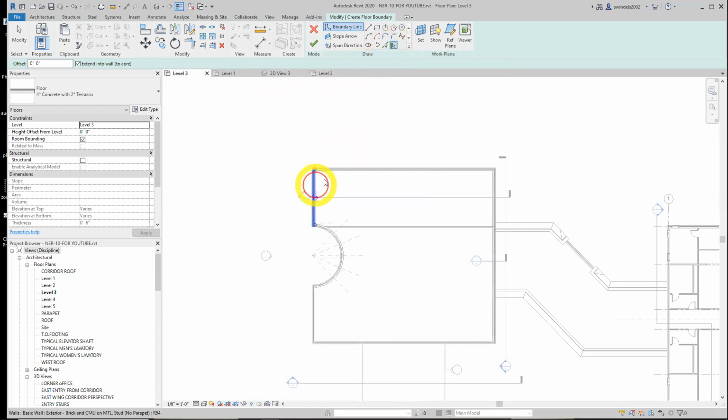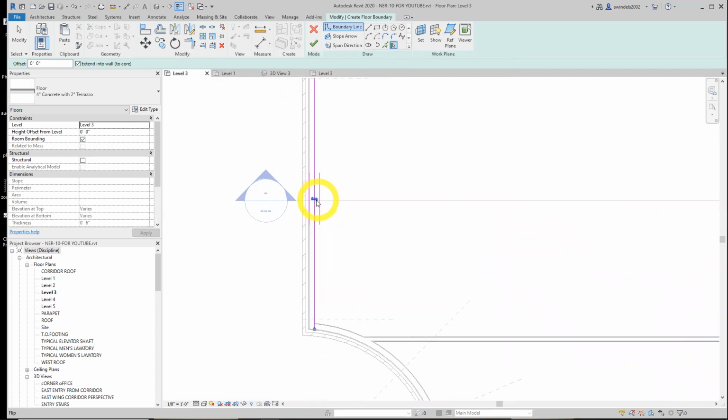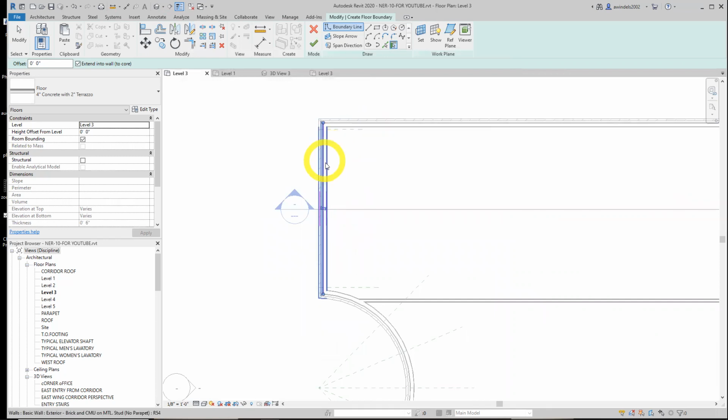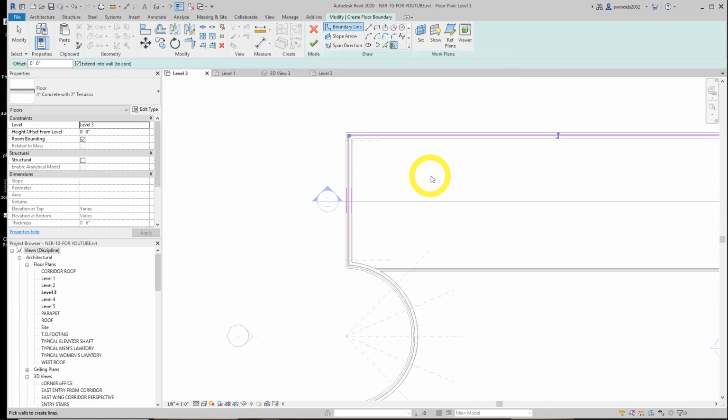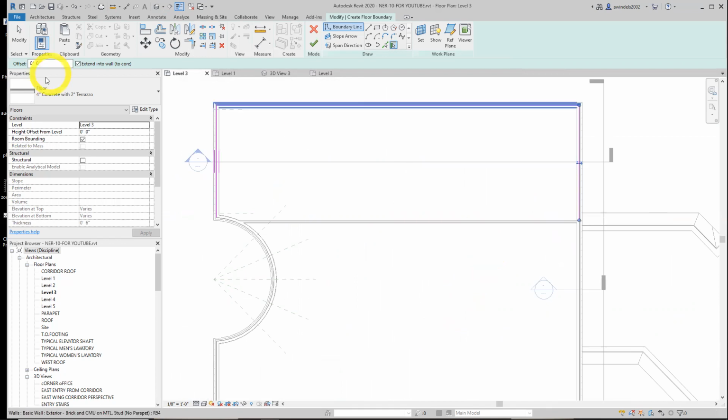Pick this wall. Or make sure it goes to the core of the wall. Since we're up from the main floor, we want these floors to go into the core of the wall, the structural core. So that's where it should be. See the magenta line there. Pick this wall. It'll match into it with it. The first one's key though. And for this last wall, let's select offset 5 feet. Or it says to pick line.